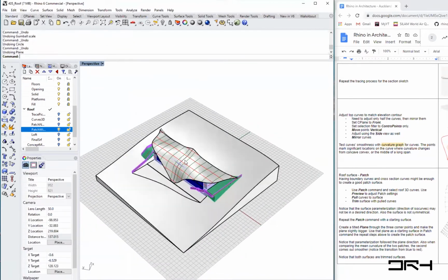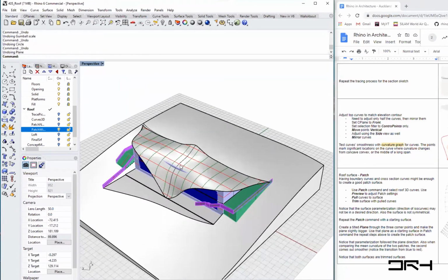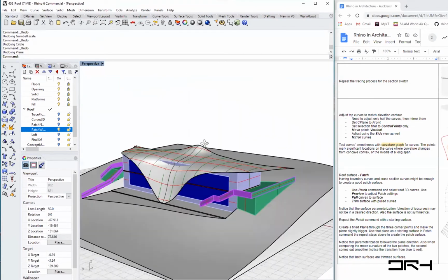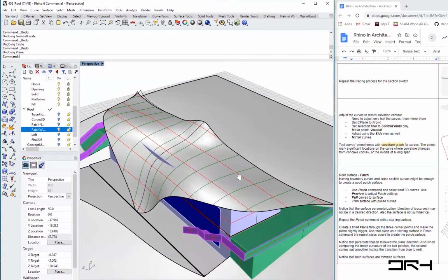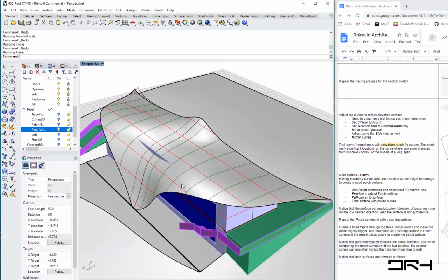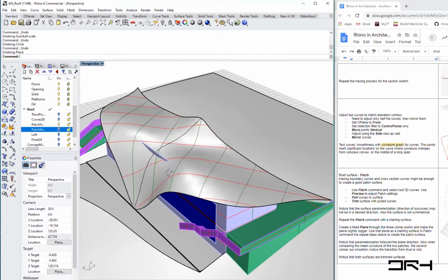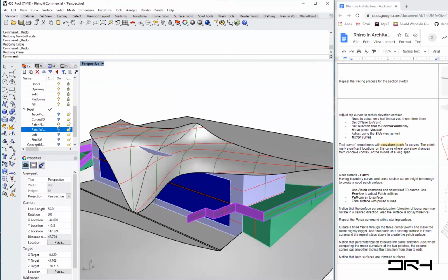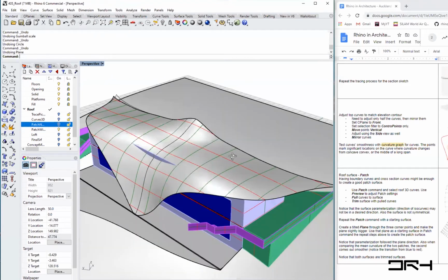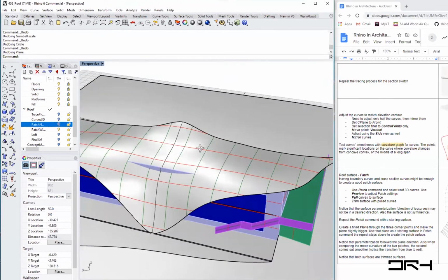So what we will do is we will try to recreate that patch surface using Loft. And lofting gives you a lot more control, as I mentioned. Remember when we created the patch to start with, it was not symmetrical, and there is a chance even the one that used the base plane is not completely symmetrical.